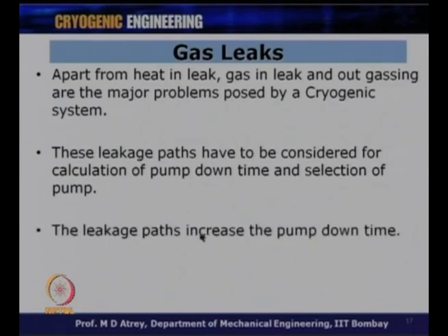The leakage paths increase the pump down time. The more the leakage paths, the more time it will take to reach the required vacuum for a particular application. So, I should know all these leakage paths, and I should know all these quantities that are leaking, and what the gases are also. I should have an estimate for those things also.